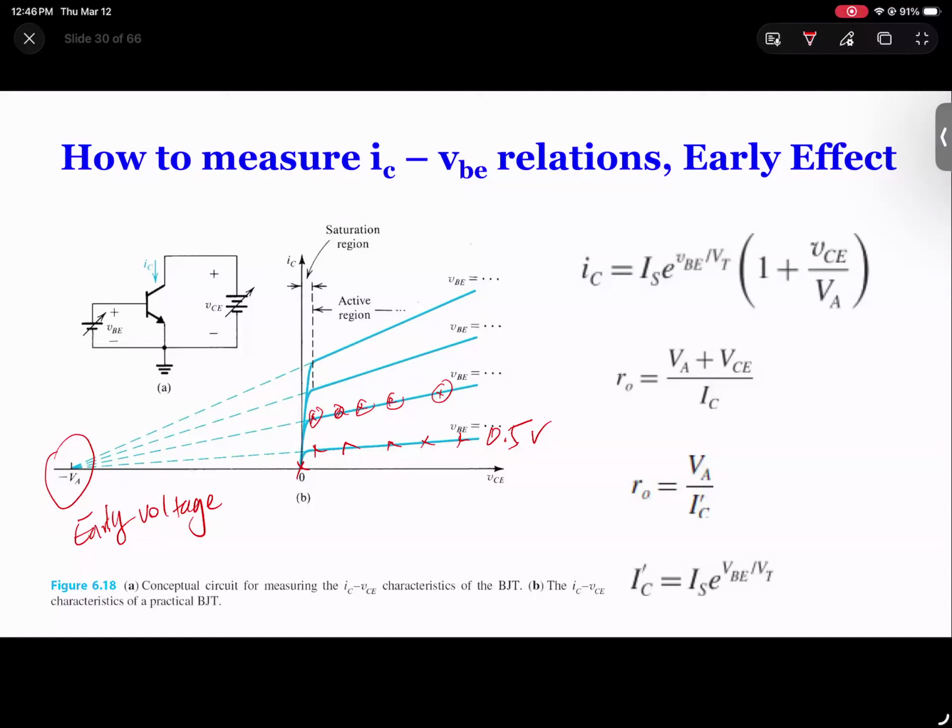But if you go slightly beyond 0.7, the current is going to increase dramatically. And if you go to 0.9, your circuit is probably going into saturation already, and you're going to have a lot of current from base to emitter that you might actually burn the device. So since it's so sensitive, we don't recommend doing this by hand.